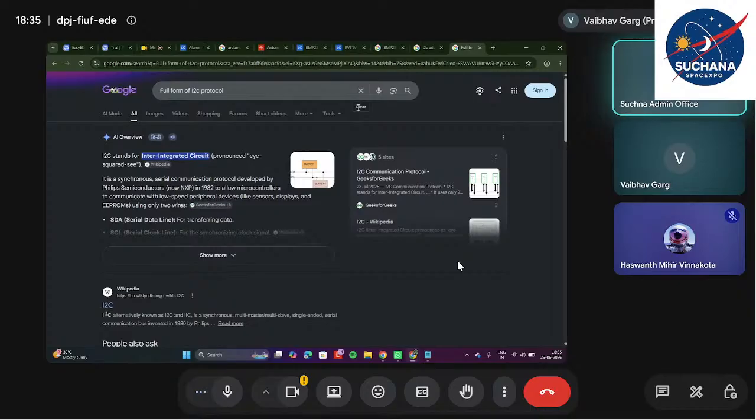This is actually called an I2C conflict error, because both sensors are trying to send data and both have the same I2C address. So how will the Arduino manage whether the data is coming from sensor A or sensor B? It's not possible. That's why the engineer gave an option. If the SDO pin is connected to ground, the I2C address will be 0x76.